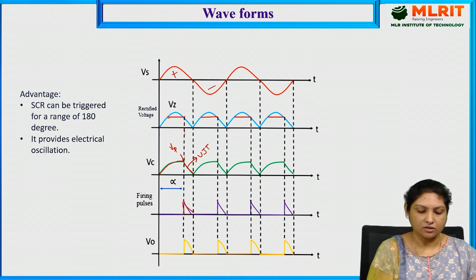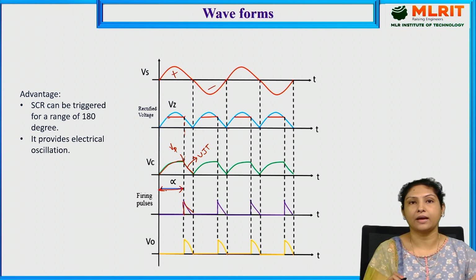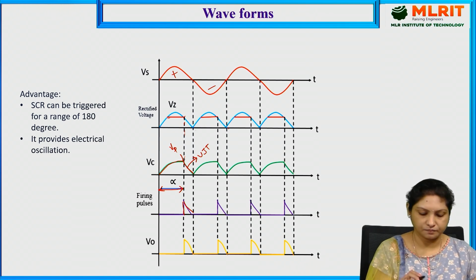And this is nothing but the firing angle of the circuit. So during this period, from 0 to this instant, the SCR is off, whereas the SCR will be turned on from this instant to this instant.